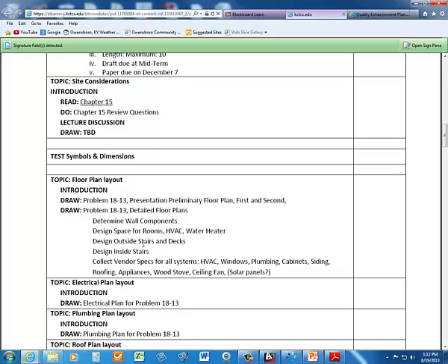The size of it can't change, and basically the style of it cannot change. It's two-story and the shape doesn't change, but the way it looks can: the exterior finish, how you want to finish it inside, and how you want to construct it. Do you want a platform frame with 2x4 or 2x6, or a beam and plank?